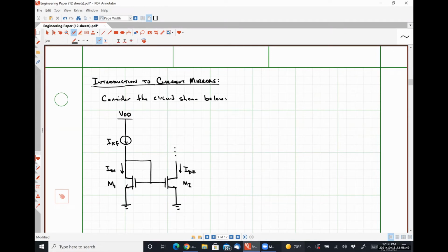While we're absolutely going to talk about their nominal utility of replicating currents and all that kind of stuff, we're going to be approaching current mirrors a little bit differently in this class than we did back in our analog and electronics classes. We're going to be treating this as a sort of biasing circuit, or effectively, we're going to say, how do we make this thing behave like a current source for other stuff, right? And I know that for now, I'm approaching this in a magic space where we actually have current sources available. Okay, and we'll fix that in a little bit, all right?